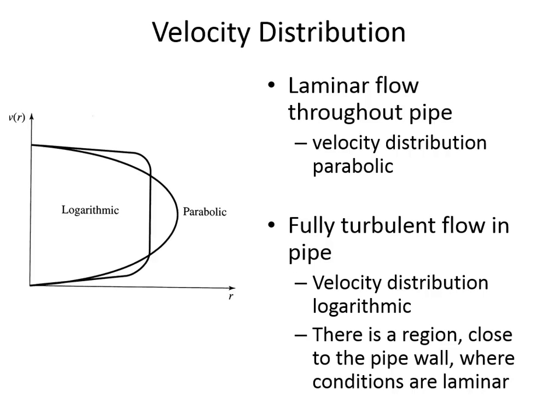So if we're looking at a cross-section here, the velocities will be the highest at the center of the pipe, which is further away from the pipe edges. Here at one edge of the pipe, the velocities are going to be 0. And then up at this pipe diameter, whatever the diameter might be, again the velocities are low because that's another surface that the forces are being applied from.